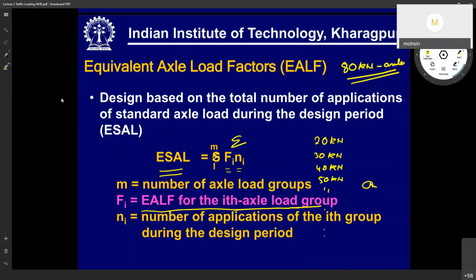No, we do not calculate in IRC 37 as well. We just calculate the tensile strains. But what I'm saying is, when they were developing SP72, they did this exercise for different CBR values. What is the elastic modulus? When the responses are obtained and put into such performance models, what thicknesses are they getting? They have given those indicative thicknesses directly, because to make the job of the designer easy, they have done that in the background.